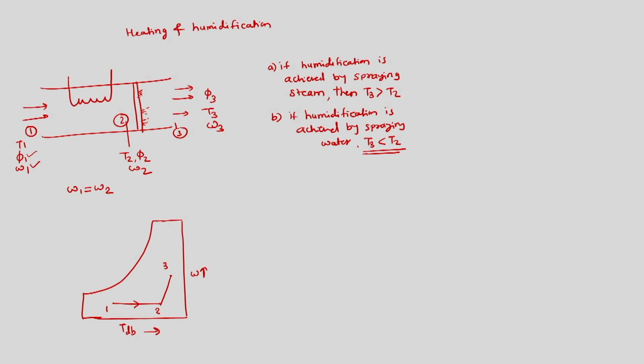If we are spraying liquid water, then the water will evaporate and take latent heat from the air, and in this case the air would reduce its temperature. So T3 might be lesser than T2. Now we can have the next process, which is cooling and dehumidification.